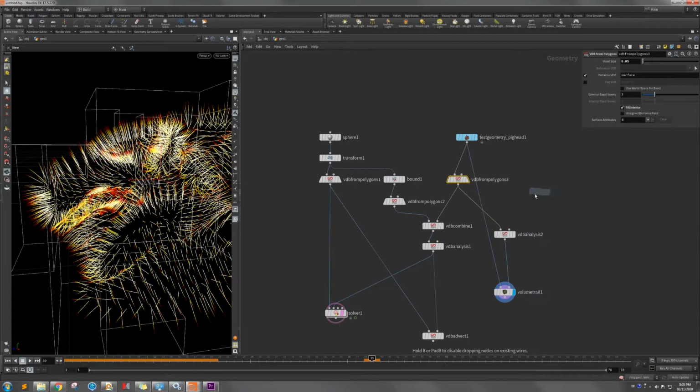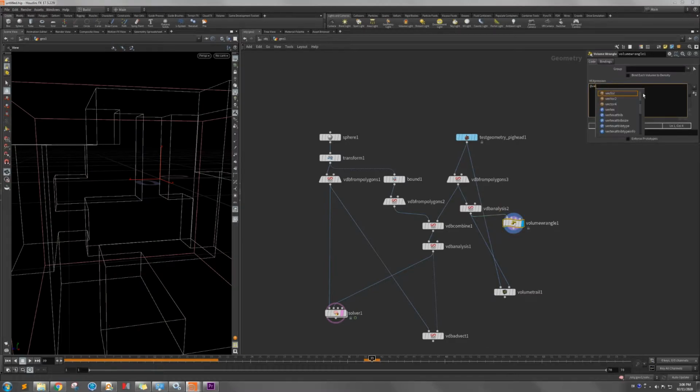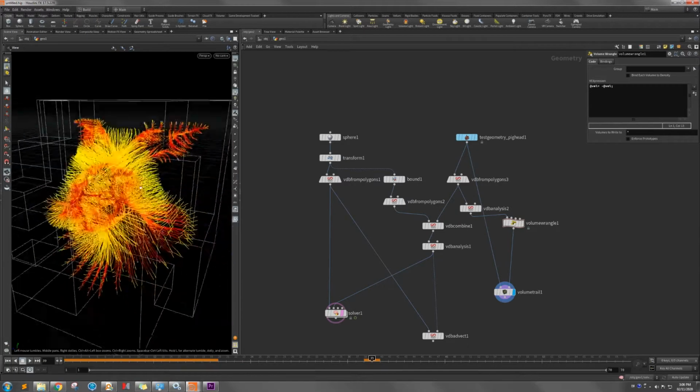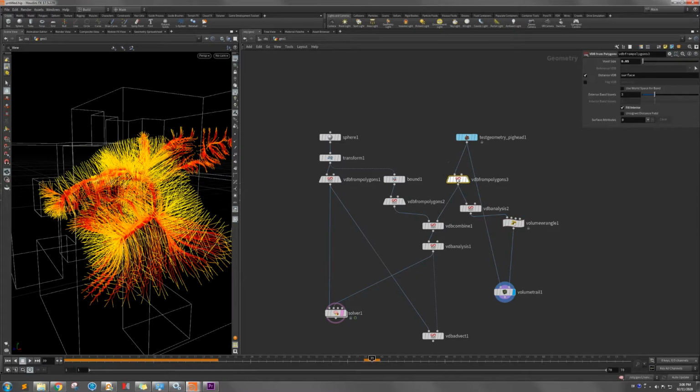Here is the example. So if I use the volume wrangle, we need to do some change here to make it work. What I want to do is change the velocity direction. In this wrangle, we just reverse the direction of the velocity. I put it here. You see, that is very close to the one we use from the fog VDB. We can do the comparison here.